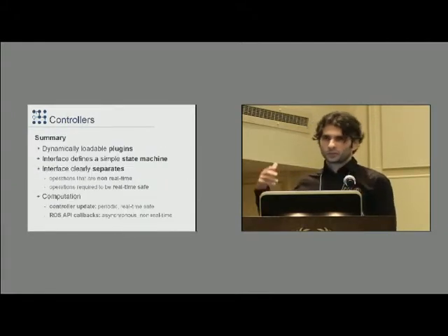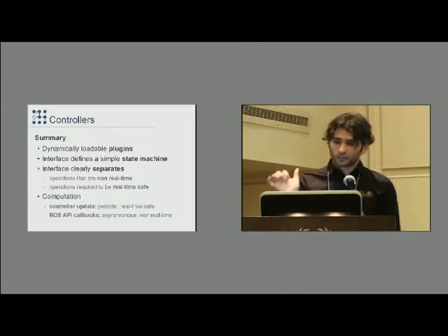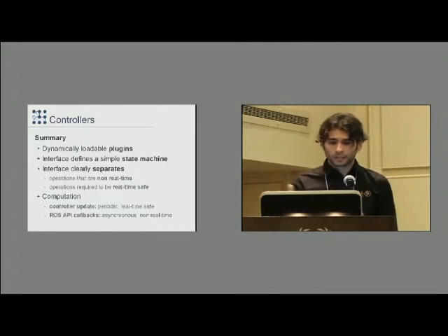So if we sum all of this up, controllers are dynamically loadable plugins that have an interface that defines a very simple state machine. This interface clearly separates the operations that are non-real-time safe from those that are required to be real-time safe. The computation can take place in the controller update, which in this case is both periodic and real-time safe. And then you have computation in the ROS API callbacks, which is asynchronous and non-real-time safe.